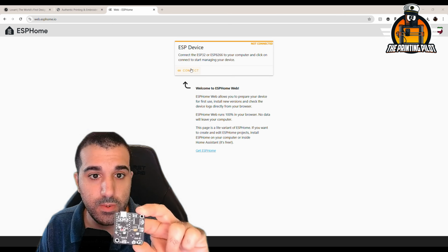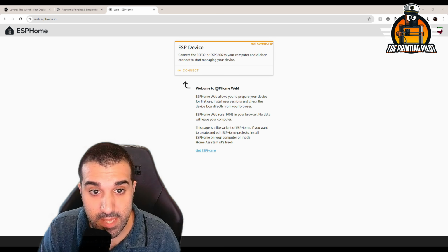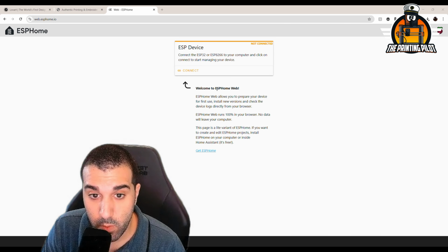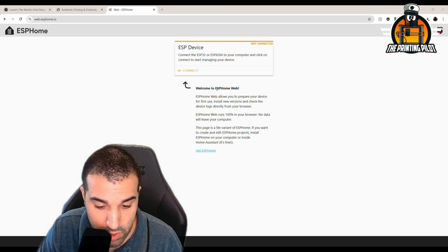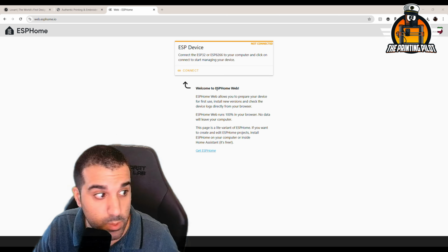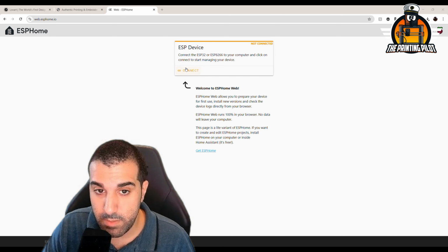But what we're going to do now is we're going to use the two bin files. So we have two precompiled bin files, one of which will spin the motor clockwise and one of which will spin the motor counterclockwise. So if we finish this process and we finish assembling everything, and while we're testing the motor we see that the motor spins the wrong way, we can come back to this process and install the other bin file, and that will fix the issue. Or also here, if you are into soldering, you can just desolder those wires from the board and switch them. So for now, we're going to install bin number 1.